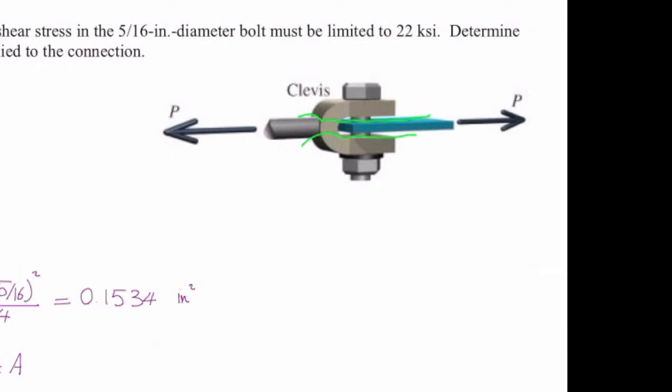So for the record, the question is why we considered P, not 2P, in this analysis, and I'm explaining why we didn't do that. If I take out, say, the right part of that, there is one plate, there is one force, P goes to the right. What else? What did we cut here? We cut 2 bolts, okay? So we need to put 2 forces on the cut section. There will be one force over here and one force over here. How much would be the magnitude of the force on each side? P over 2.